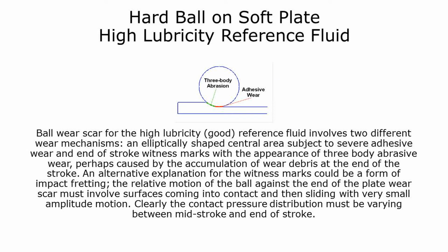It is apparent that the ball wear scar for the high lubricity reference fluid involves 2 different wear mechanisms: an elliptically shaped central area subject to severe adhesive wear, and end of stroke witness marks with the appearance of 3-body abrasive wear, perhaps caused by the accumulation of wear debris at the end of the stroke.